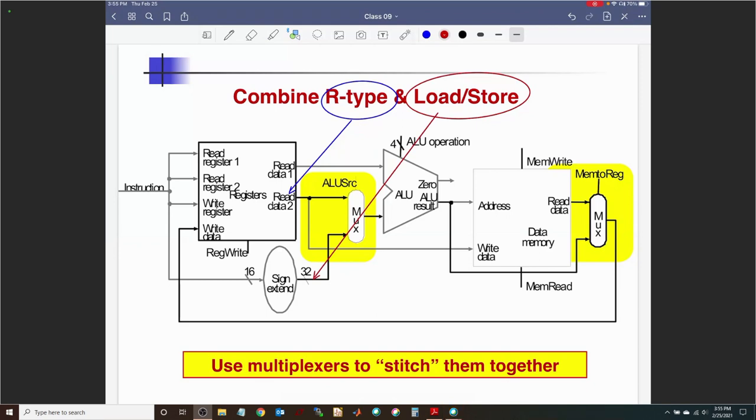See that? So you have one more bit, and we are calling that ALU source to control which particular 32-bit number comes to the second side of the ALU. In one case, for R-type instructions, it is going to be one of the 32-bit registers, and in the other, it is going to be the 32-bit sign extended offset. You see that? All right.